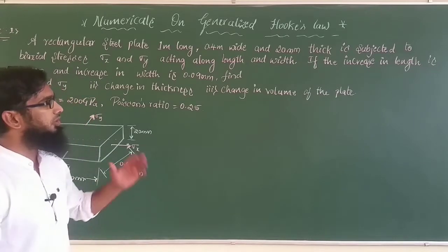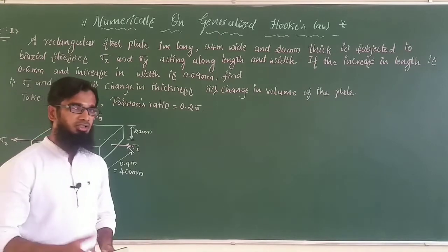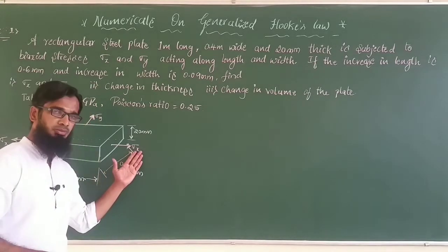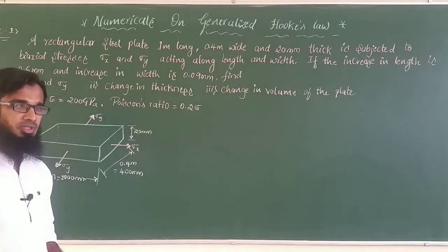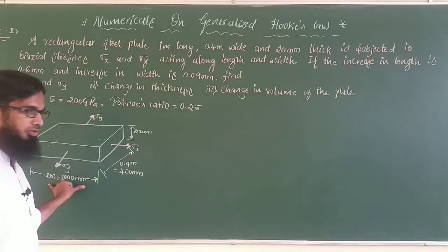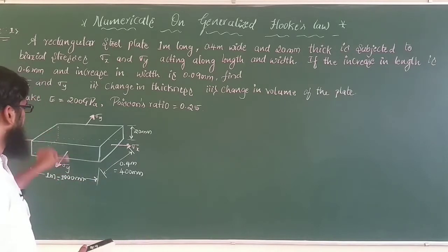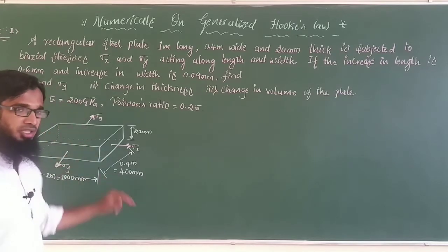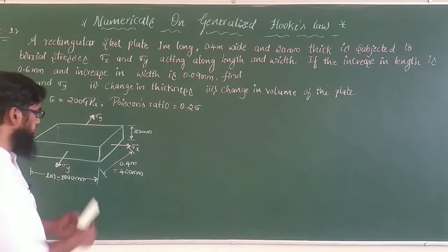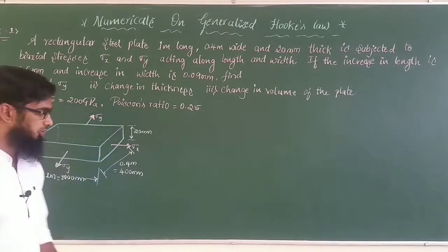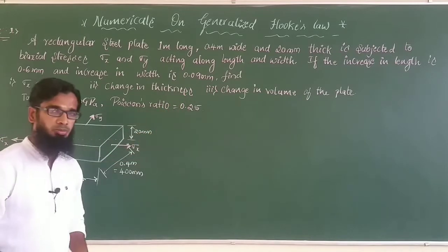Now, the increase in length is 0.6 mm. When we apply some load, there will be a stress in the longitudinal direction, and because of that applied load a deformation takes place. The deformation is nothing but a change in length, which in the x direction is 0.6 mm. Again, the increase in width is 0.09 mm, because of sigma y.